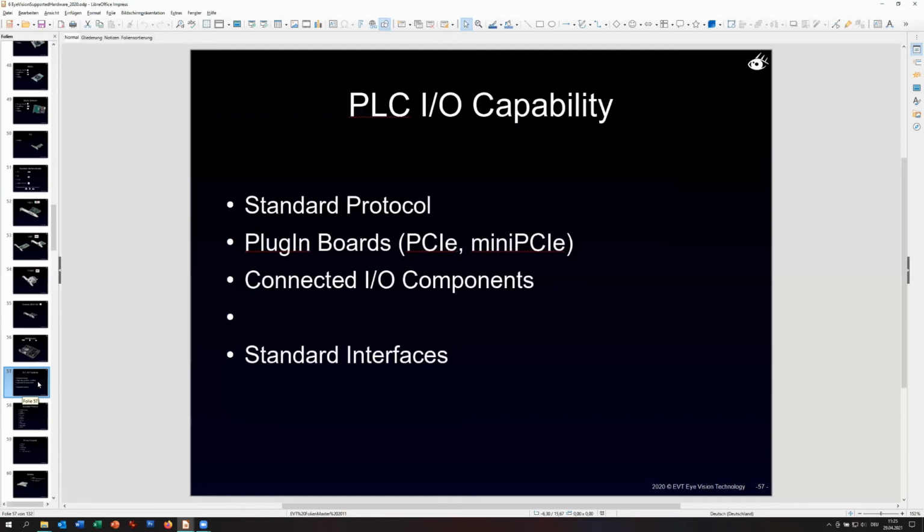And therefore, you have to connect the camera or the system to an encoder. You can connect the encoder either to the PLC, or in most cases the cameras have a direct encoder input, which many of the 2D cameras also have.